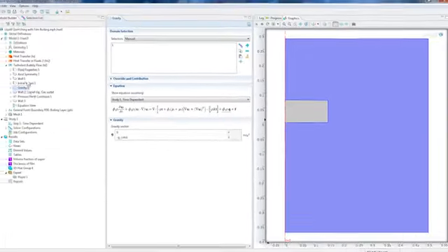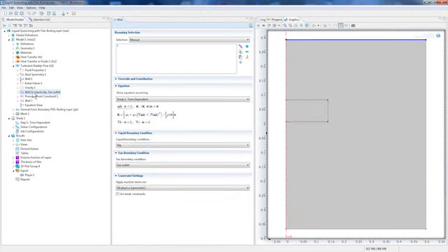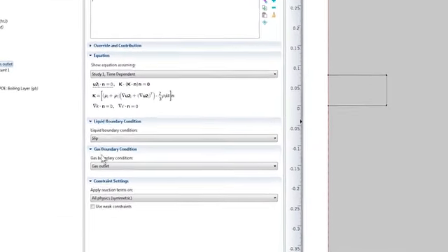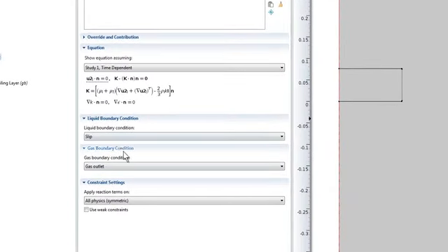The wall 2 boundary condition here, applied to the top of the fluid domain, allows for the liquid phase to flow tangential to the boundary, but not normal to it, while at the same time allowing the gas to flow freely out of the domain. These conditions are set up here. One really nice feature in COMSOL is that if you ever have any doubt about what boundary conditions you are applying, you can always view the mathematical equations in the settings window under the equation section here.